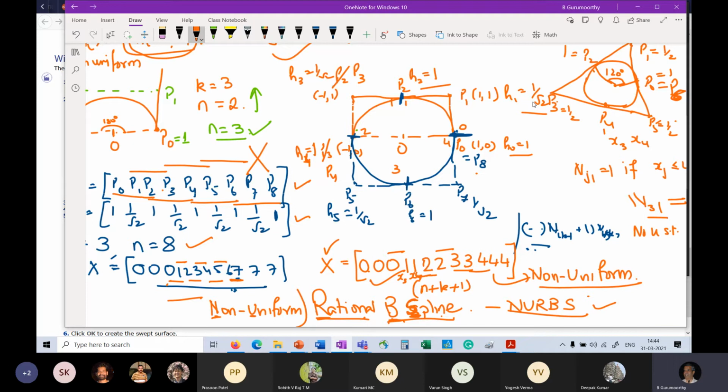Okay, so now that is the definitive solution for representing arbitrary curves and known curves, the NURBS, right? And the system will automatically choose appropriate simplifications or generalizations to achieve the representation you need. You need a circle, you will have non-uniform knot vectors. You need arc of a circle, then you use rational. And if you want Bezier, you will say k is equal to n plus 1.